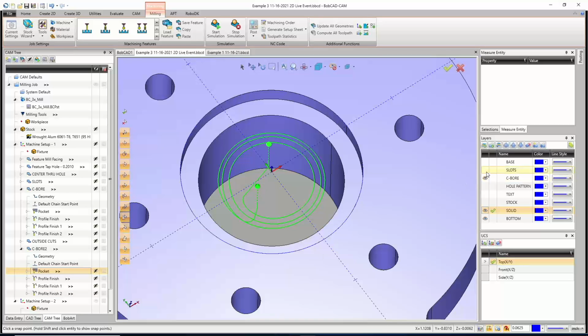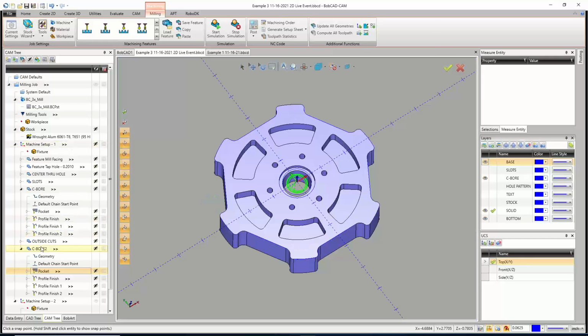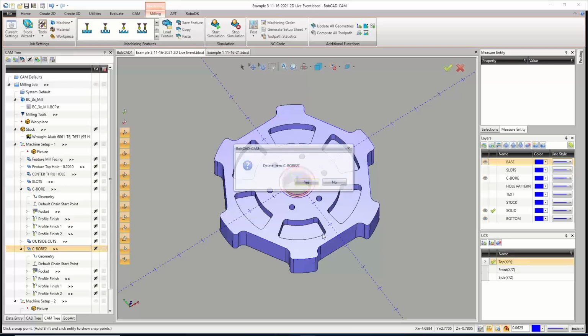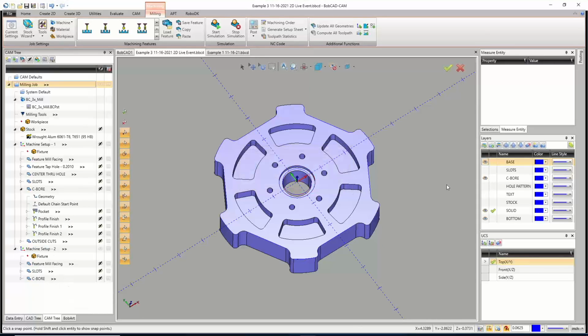It'd be the base actually. We'd have to take that arc right there and make it a dotted line. And then it would know. In the past, if you're using version 333, that's how you'll have to do it. That's how it knows that you're doing the open pocket. So detect open edges, it's a killer feature. You just pick the surfaces, but it all relies on you having those surfaces.